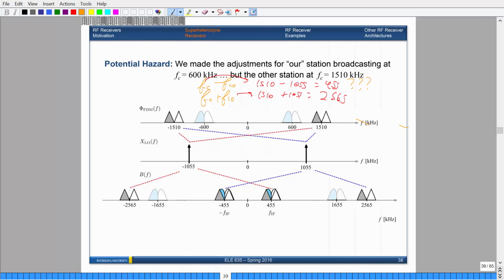So you take your center and then you plus or minus the local oscillator, and one of them unfortunately still happens to be a 455. So how exactly do you compute this number? How exactly do you get this? It's actually very simple. All you're doing is taking your carrier frequency and adding twice the intermediate frequency to get that. And that actually works out like that.